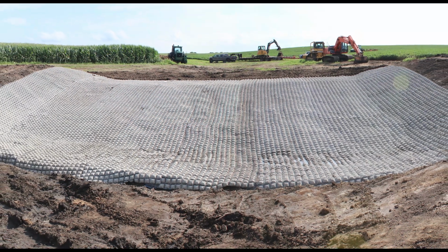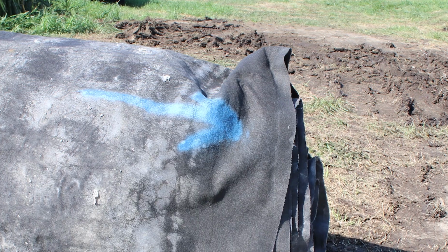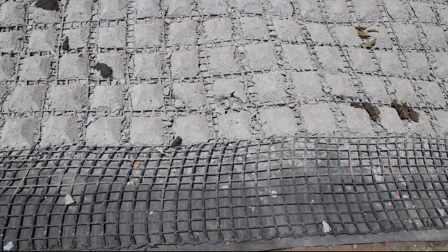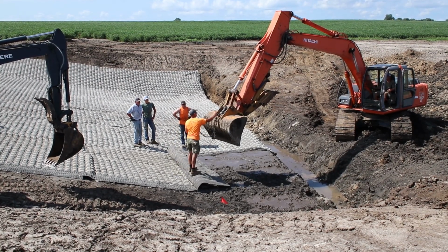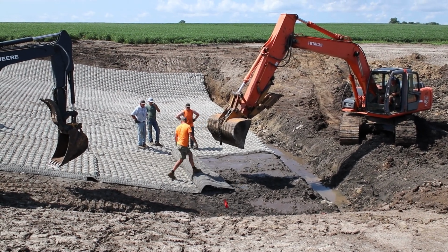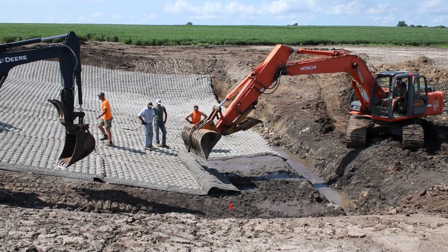That went pretty fast, but it actually took a day to install all of those rolls. The rolls are made so they overlap the geotextile of the adjacent mats. Each roll has a 12-inch extension of both geogrid and geotextile that extends beyond the blocks on one side. This extension makes it possible to overlap the second roll and each subsequent roll, ensuring there are no gaps in geotextile or geogrid that is protecting the subsoil.